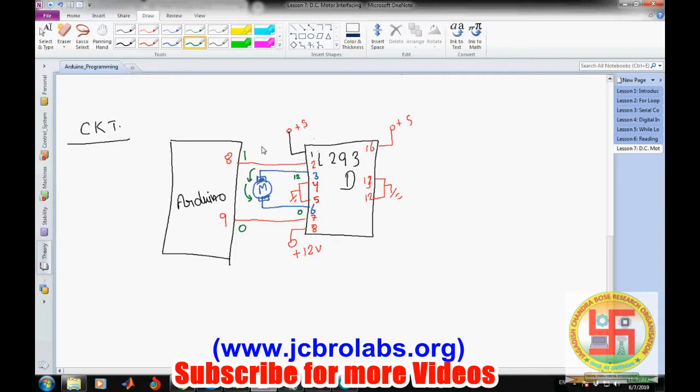Similarly, if we change this 1 and 0, making this 1 and this 0, 12 volt will appear here and 0 will appear there. Now current will flow in the opposite direction, and we can assume the motor will rotate in the opposite direction. So this is how we connect our DC motor to the Arduino UNO.